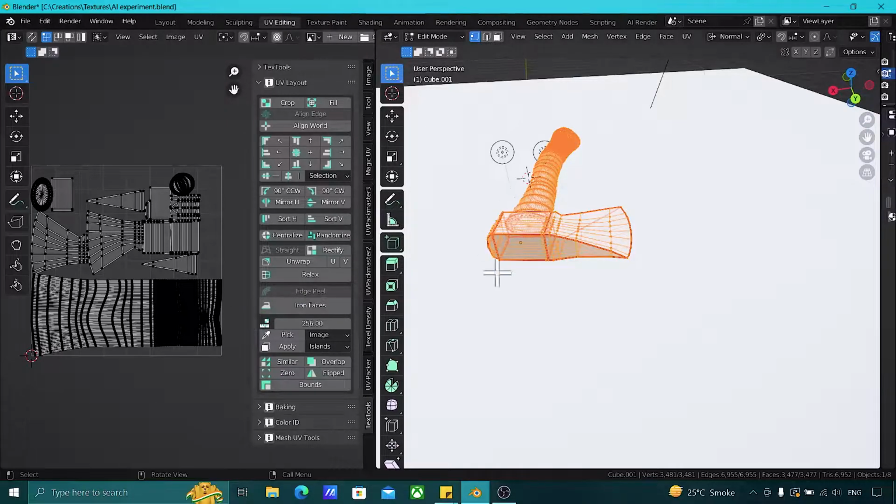When we shift the models from Blender to Unity and Unreal, it becomes problematic because what Unreal does is it triangulates the mesh, and if there is any overlapping in the UVs, it gets reflected. And believe me, it's very pathetic to see that. So make sure that you don't make that mistake, and also check the flip faces.